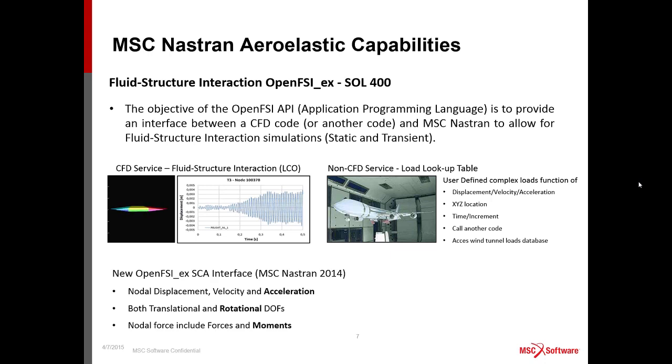table. So what I want to emphasize is that with MSC Nastran 2014, the development team has extended the OpenFSI service to the OpenFSI X interface. X is for extension, and this is very interesting because now we are able not only to pass nodal displacement velocity from Nastran to the CFD code, but even the acceleration. We implemented both translation and rotational degrees of freedom. And nodal force includes both forces and moments, and this is what was missing till 2013.